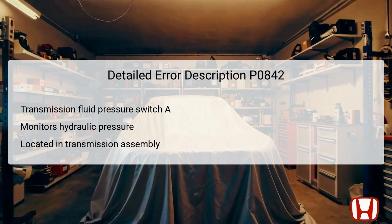When the DTC P0842 is triggered, it typically means that the switch is signaling a low voltage or an open circuit condition, indicating a possible electrical fault. This code cannot arise from mechanical issues within the transmission. Hence, troubleshooting must focus on electrical connections and the switch itself. Understanding this component's role aids in diagnosing issues more efficiently.